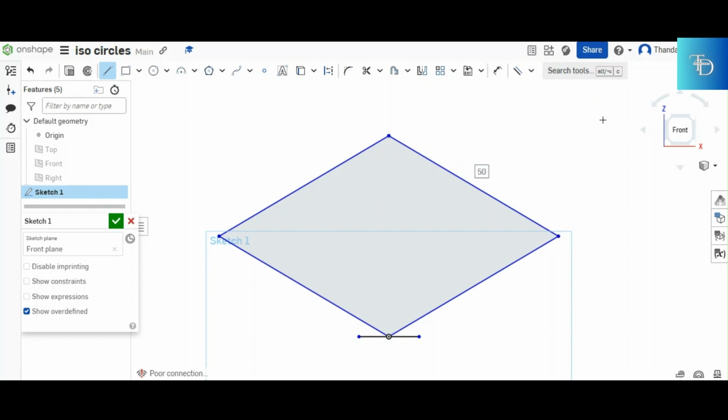The next step is you figure out the center of each side of the square. Since each side is 50 millimeters long, the center of that side is going to be at 25 millimeters. So we're going to have our 25 millimeters there. You mark the 25, you come over to the other line, you mark the 25, you go over there, you mark the 25 at the centers of the lines. All four sides, you mark the centers of those sides. And by doing that, you're already halfway there because you're only left with a few steps to complete.